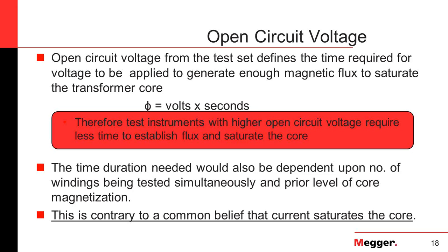So what time do we need to saturate the core? Well, that is dependent upon the winding that you are testing. In the cases of windings with very high voltages, we need more time, and so we require this time relative to windings with less voltage. The current is going to be discussed in the next slide, where we will see the importance of the current.